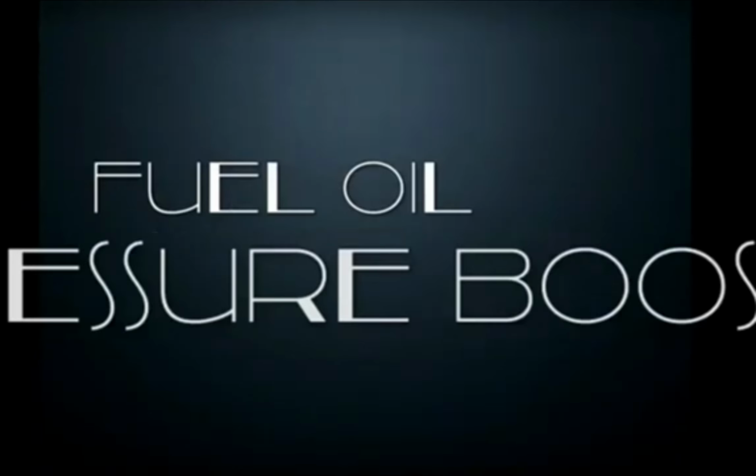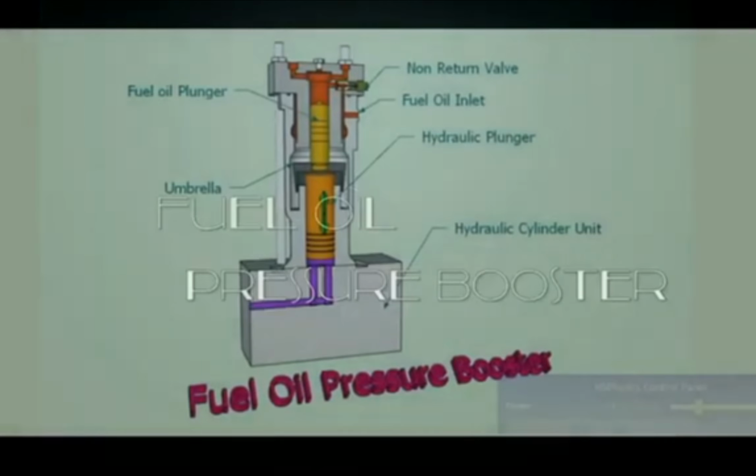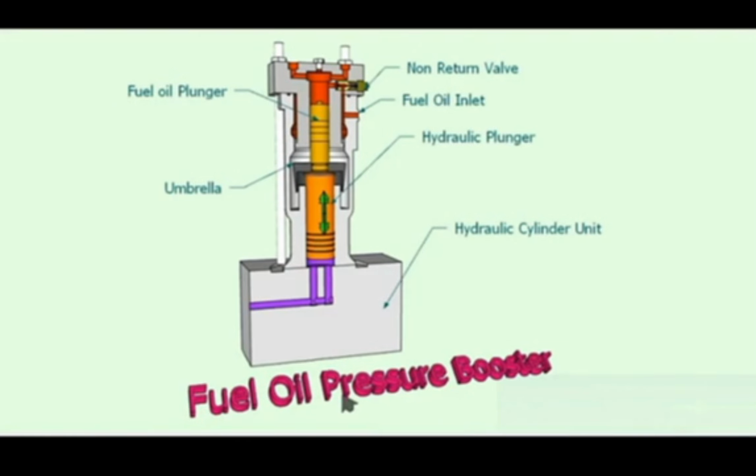exact position. Next is the fuel oil pressure booster, which is fitted on the hydraulic cylinder unit. From the LFE valve, the hydraulic cylinder unit gets a high pressure oil flow. This oil flow pushes the hydraulic piston up, and this hydraulic piston pushes the fuel oil plunger, which is in the upper position as shown in the figure. One umbrella is given for protection against spillage, to prevent any mixing of fuel oil in the hydraulic system.